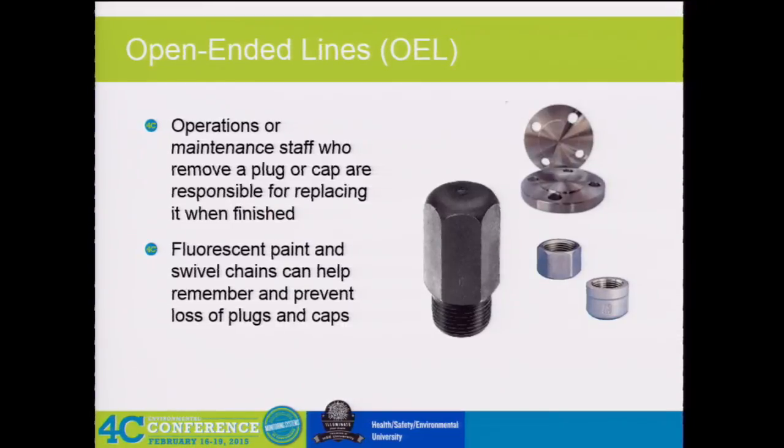So what you've got to do is basically figure out what's best for you guys and what helps minimize it. But the piece that I would go with is just add another damn valve to the end. That's usually the easiest way, because unless you're standing right there and you watch an operator or a lab tech or somebody open that and close it, I have no proof that you didn't close the upstream valve first and the downstream valve second.